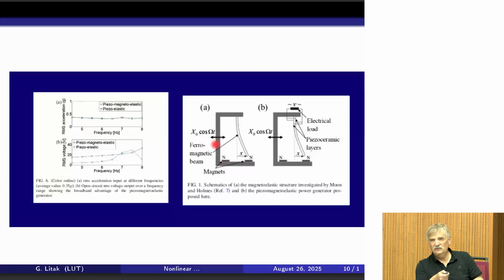excitation. Larger excitation usually means larger amplitude, but it is also related to the frequency, because if we are closer to the natural frequency of the beam, of this first mode oscillation, we can lower the amplitude a little bit, because this would be very efficient.